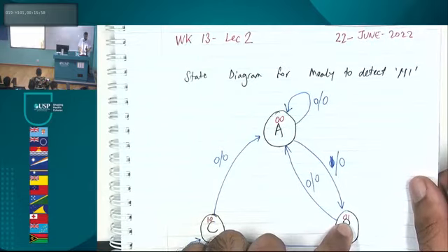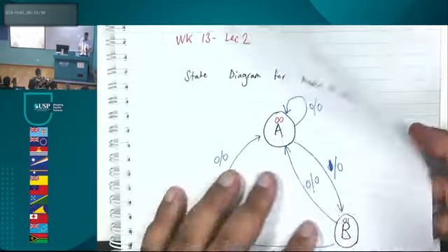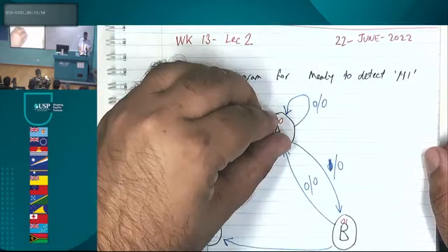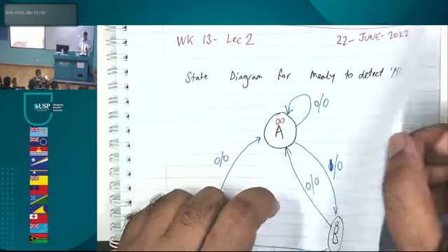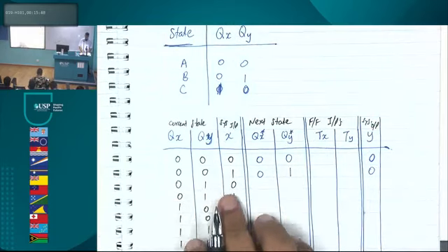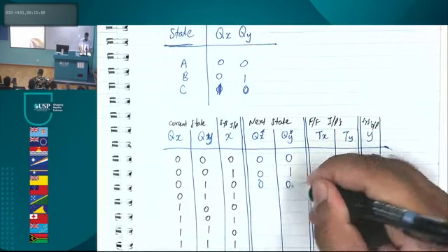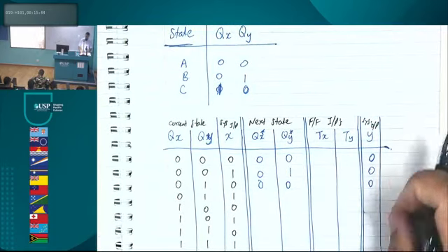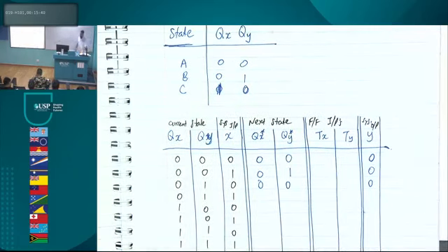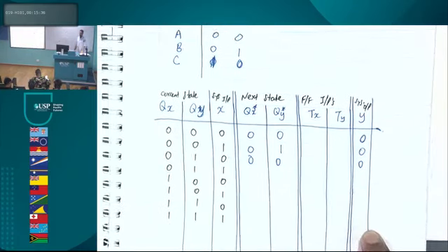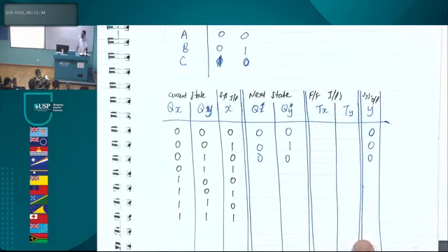Now, 0, 1, see 0, 1 is the next one. So we now sent it over here. We've done and dusted this. 0, 1, input 0 goes to 0, 0, output is 0. We know our sequence detector in this lane will only come to 1 once. There will only be one 1 in that particular Y lane.